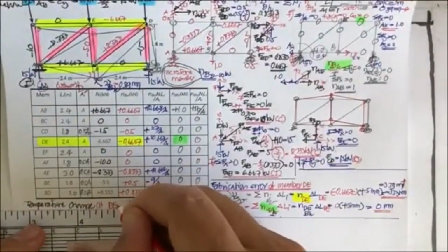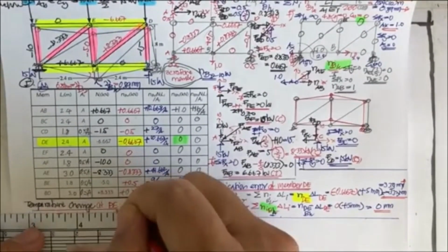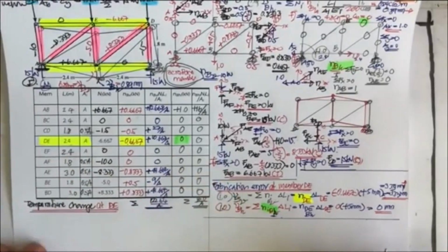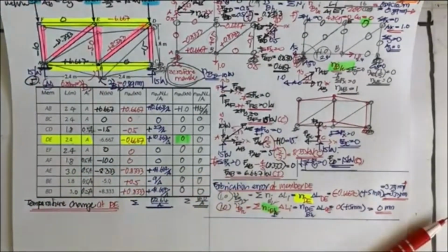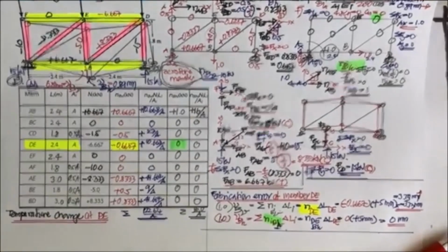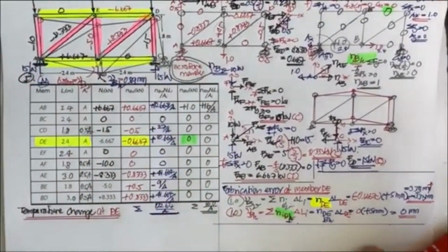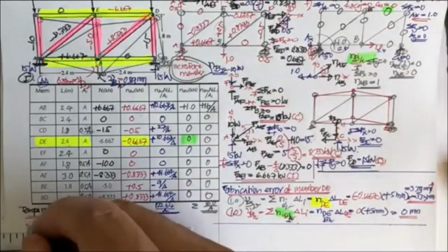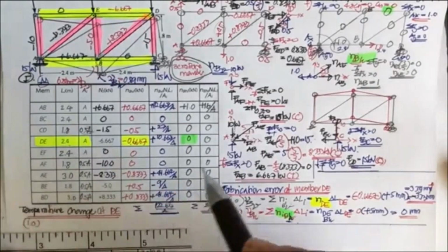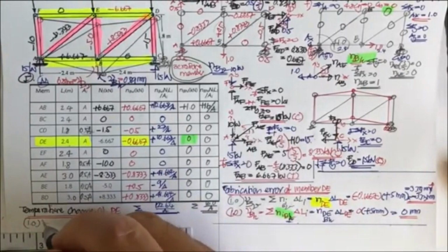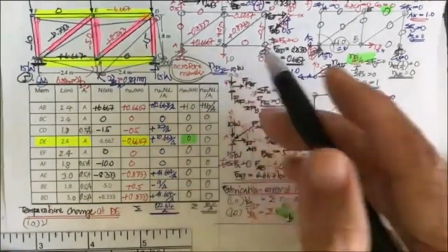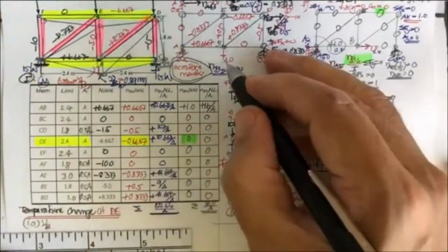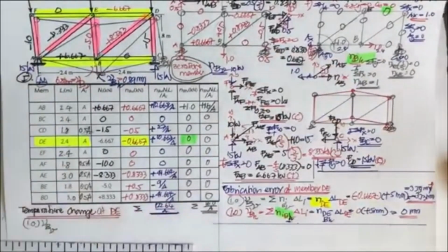Okay. And now what equation do we have? It's going to be the same thing. It's going to use the virtual work equation, but this time you're going to put 1.0 in which direction? In the direction of deflection, at point B in the vertical direction.